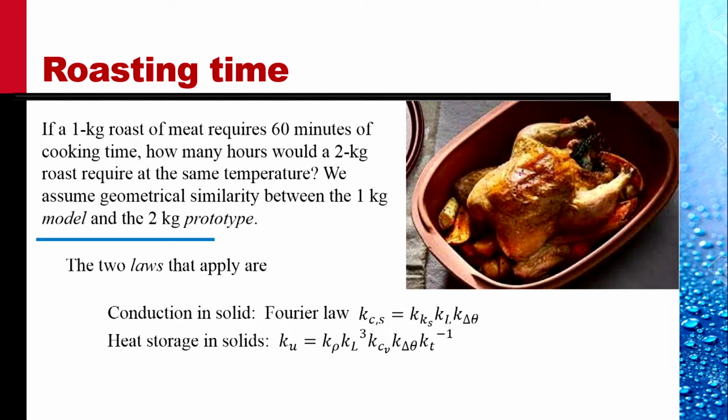Okay. There are two laws that apply: conduction in solids within the chicken meat, Fourier's law, and this is the relationship for the scale factors, and the heat storage within the solid. We assume the temperature at the surface is constant in either case, and this scale factor is given by this relation.